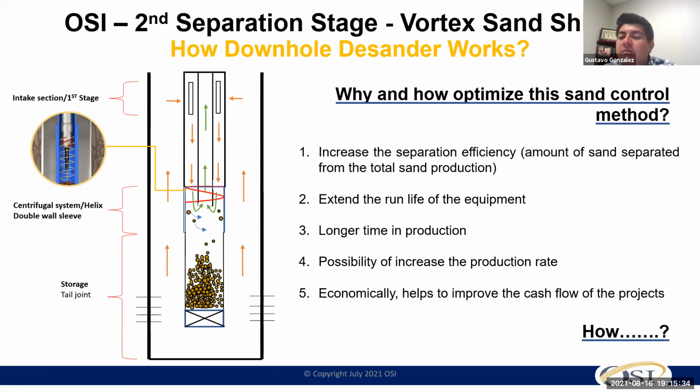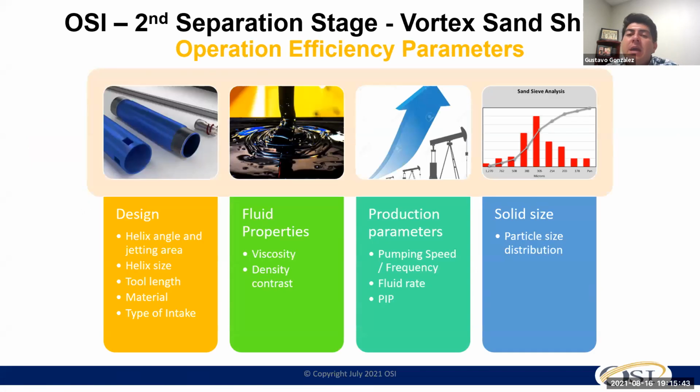That's where you see the differential factor: instead of pulling this well once a year or 3 times per year, you move that needle and go one every year, or in some cases they go from one ESP immediately to rod pump, because you're able to keep this well and hold for a year and a half or 2 years, to the point that now the failure is more because you have an oversized ESP and it's too big a pump for the amount of ratio that is passing